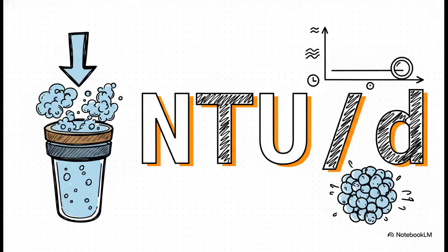So the absolutely crucial point we need to focus on is this number right here, 0 NTU per day. NTU is just a standard measure for water cloudiness. By plotting the change in turbidity over time, they created what's called a turbidity breakthrough slope. A slope of 0, that means the filtered water is staying perfectly clean. It represents incredibly strong flocks that literally never break, even under the maximum pressure building up inside the filter media.